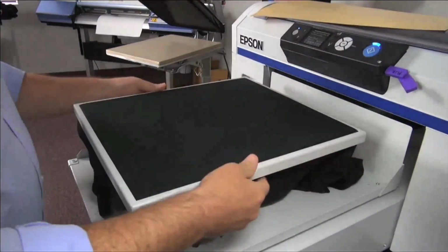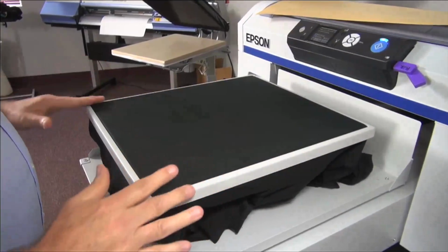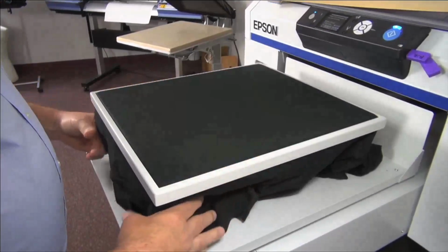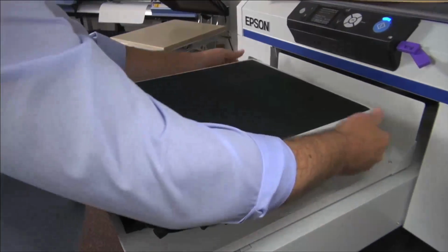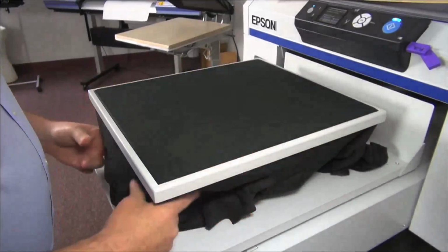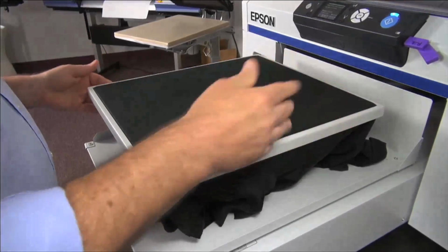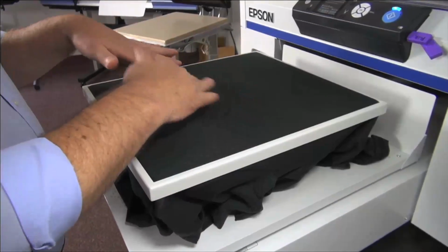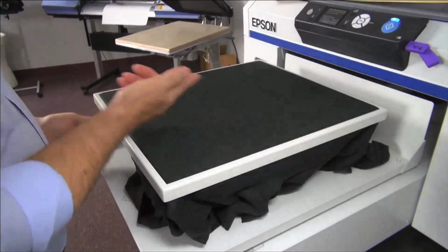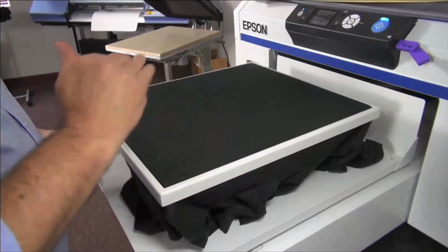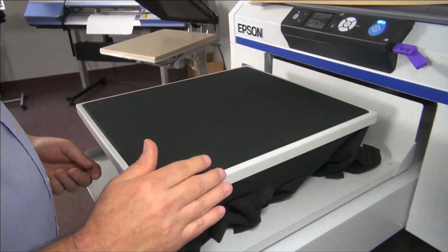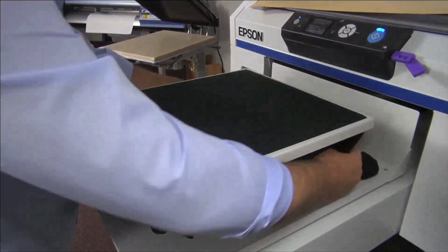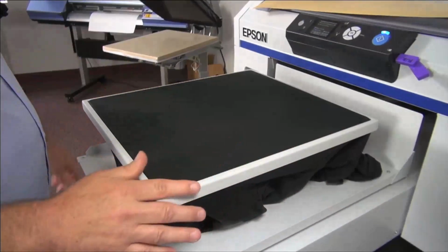So I've loaded the shirt on. This is a 14 by 16 platen. We're going to use a ring around the outside, which is kind of just like an embroidery hoop, just to hold it in place. The good news about this particular device, this is the Epson F2000, is that if I get this shirt a little too high, with too many wrinkles in it, there's a laser that shoots across here that lets me know that I have a chance of damaging a printhead by hitting the printhead, so it will reject it and say try again. In that case, I'll either lower the platen or I'll just fix the wrinkle in the shirt.